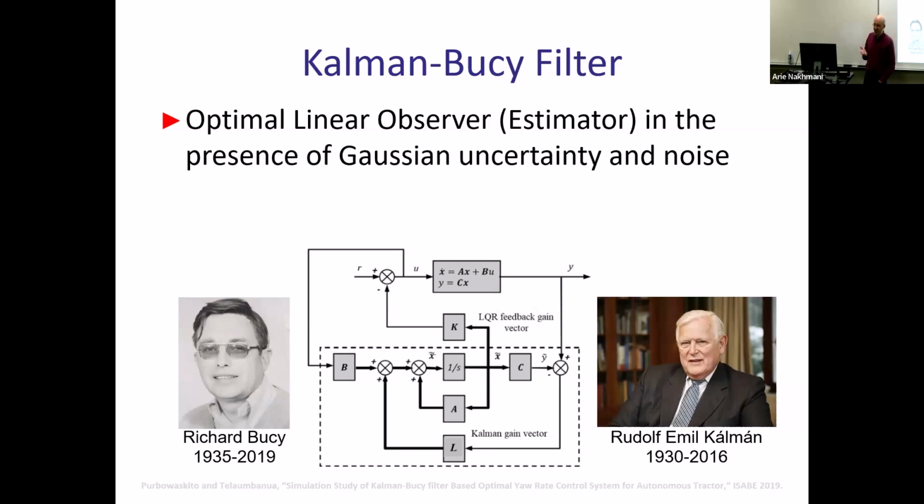So practically speaking, this is the optimal linear observer for continuous time systems, called the Kalman-Bucy filter. All right, developed by Kalman and I assume his student Richard Bucy. And it's not different from connecting a regular observer to a regular controller in state space, which means if you're looking at the diagram here, you have some system with inputs U, outputs Y, and then you have maybe some reference or maybe not. And then you are modeling that entire thing given matrices A, B, C, sometimes even D.